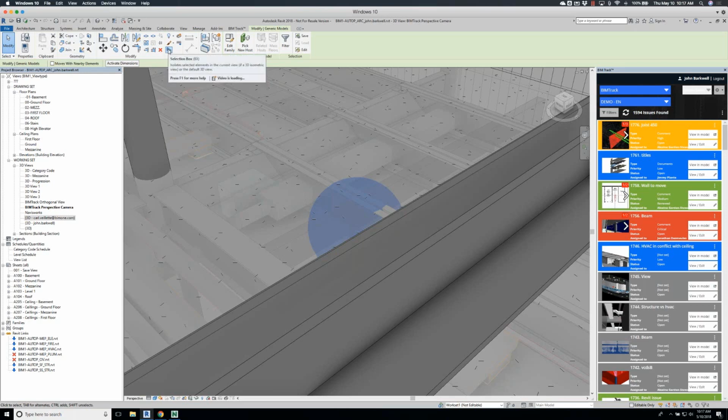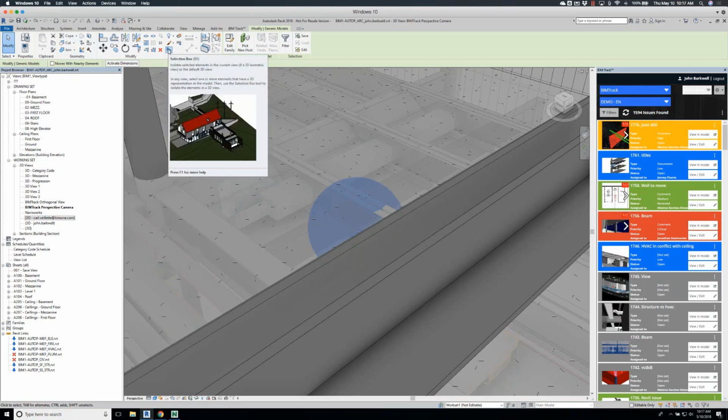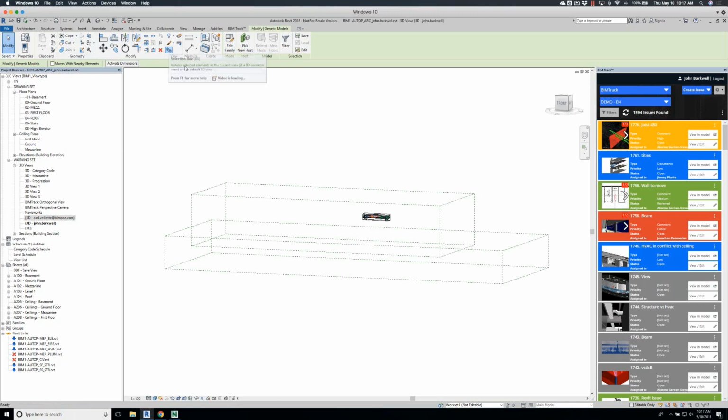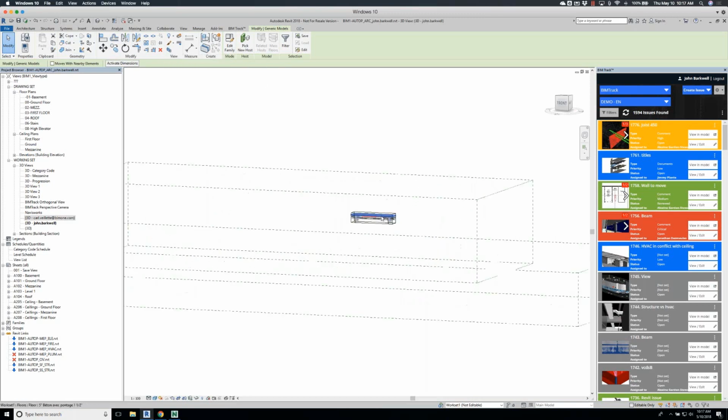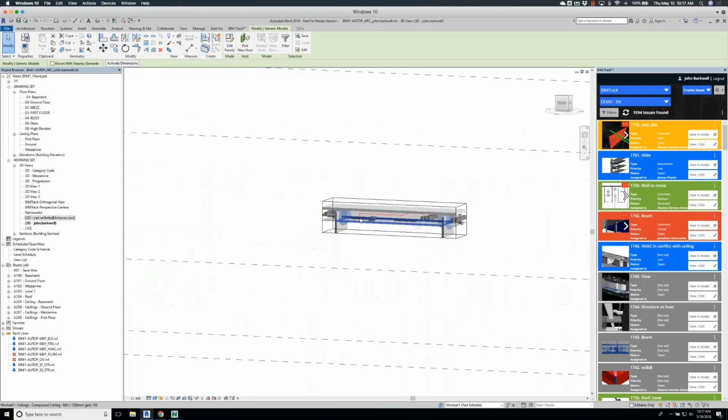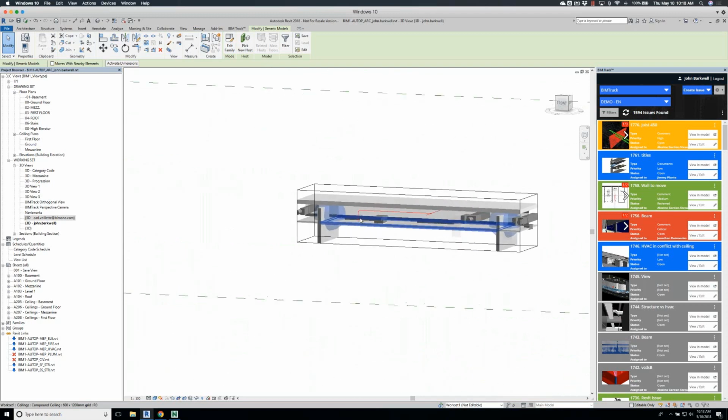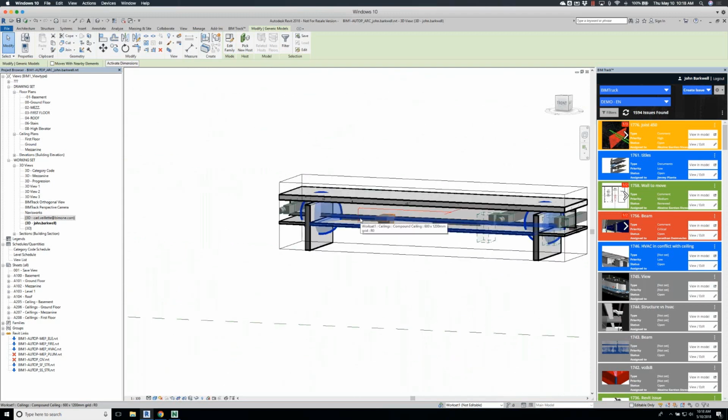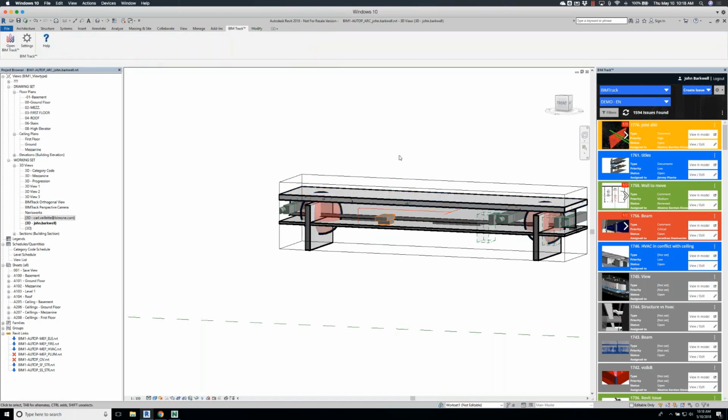And then using the selection box tool inside of Revit, if I go ahead and click on that after doing that conversion, you can see what it does is it clips around, because a lot of times when you get clashes, there may be some elements that are in front of you that you really can't see where that clash is at. So simply using the selection tool, when the spheres were automatically selected when I clicked on View and Model, allows me to very quickly pinpoint where that clash or concern is at, okay?